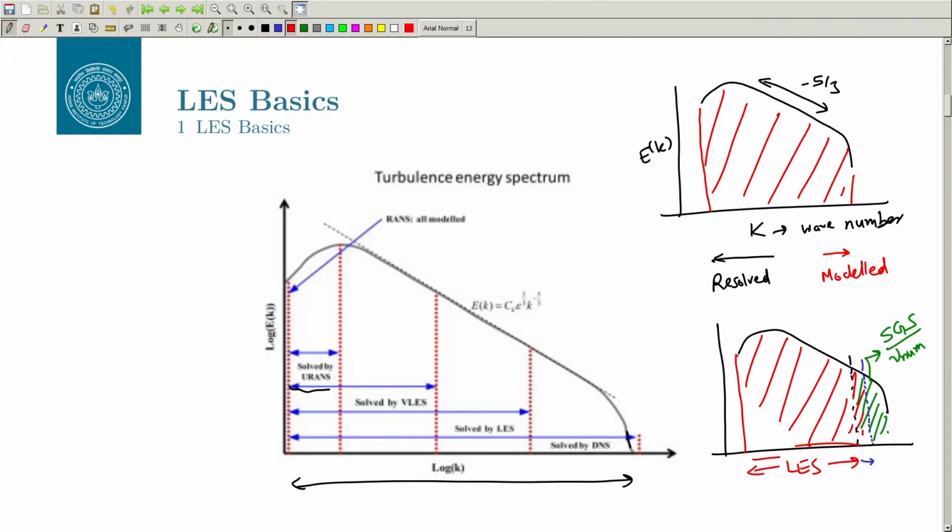So, they are going to change, right. So, maybe when you compare the mean flow, then you can justify that as you resolve the grid, the mean parameters did not change. So, that could be one of the ways to discuss grid convergence in the LES, but otherwise if you look at the turbulence quantities, the behavior of the eddies, okay, they will be different as you work from a coarse grid to a finer grid, okay. Simply because you are resolving more and more spectrum.